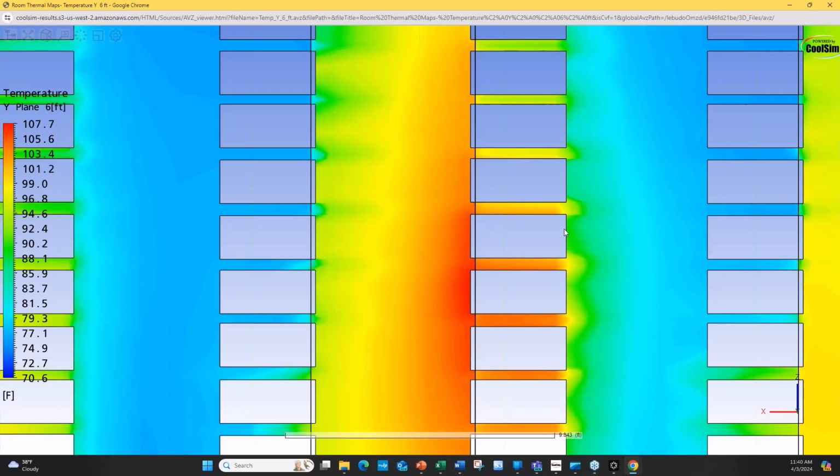You know, Magnus, I was working on one of these for one of the national laboratories, one of the smaller data centers, and they had sent me thermal data. And the only way I could get the thermal data to match this model data, the simulation data, to calibrate, was to open up the leakage to almost 100%. And I called them, and we did one of these reviews like this, and I showed it to them.